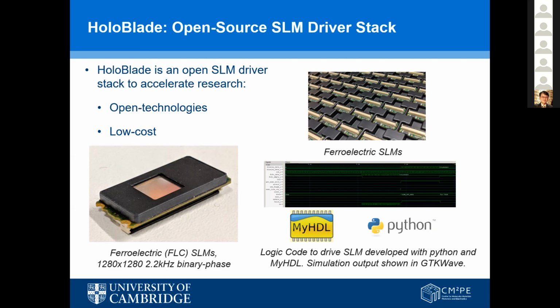I'm going to go on and talk a bit more about the interface I've designed. One thing which I think is technically quite interesting and worth highlighting is that a lot of the comms interface has been implemented in an FPGA as custom synthesized logic. To do that, we used Python and a tool called MyHDL, which auto synthesizes the logic, and that's been very good to use. So I just want to put in a cheeky little plug for that here.